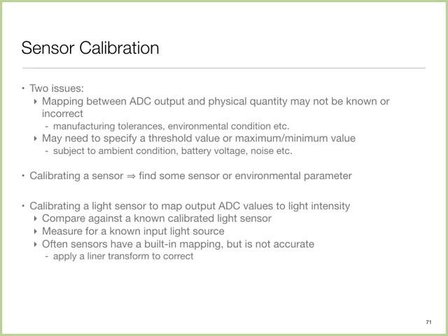Another thing which is done is sensor calibration. Sensor calibration deals with the signal that you are getting and how you are mapping it to the physical value of interest. There may be a lack of calibration in it. For example, if you have a sensor reporting your heart rate, is it doing it correctly, or a weight sensor? Usually sensors have some calibration procedure. Some sensors are pretty bad when it comes to calibration. They require a lot of effort.